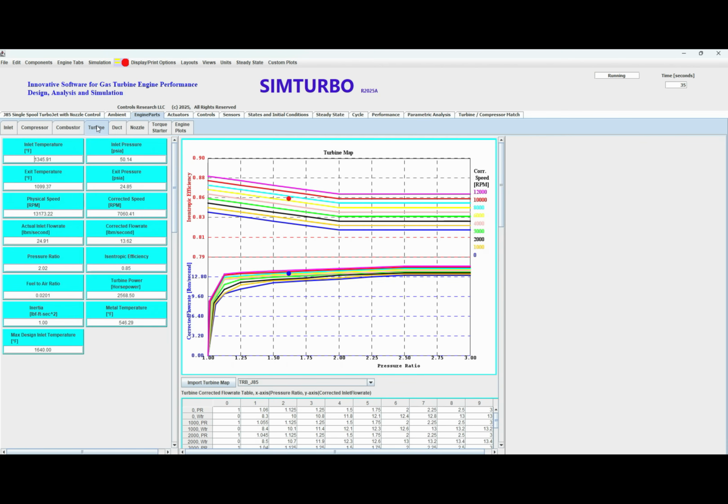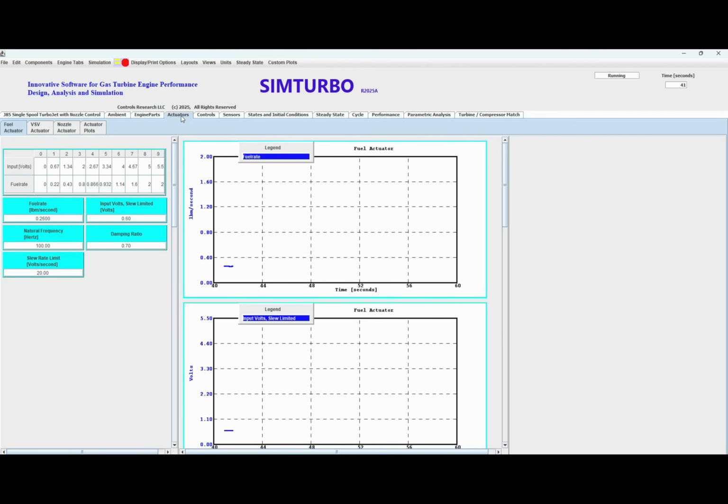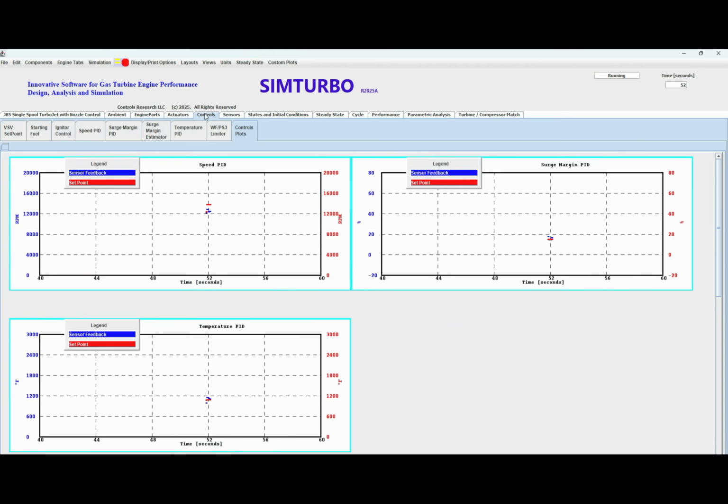The software uses high-speed, zero-dimensional (0D), or sometimes one-dimensional (1D) lumped parameter models. Component maps are key here. And that speed is absolutely vital for dynamic and transient analysis. Think throttle slams, quick power shifts, and probably most importantly, validating the FADEC's response to those events. It makes it perfect for rapid software-in-the-loop testing. SIL testing. Right, SIL.